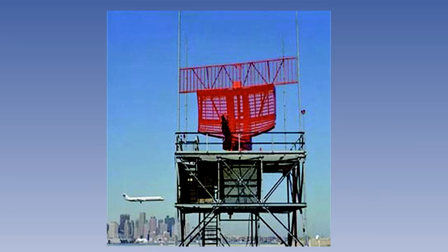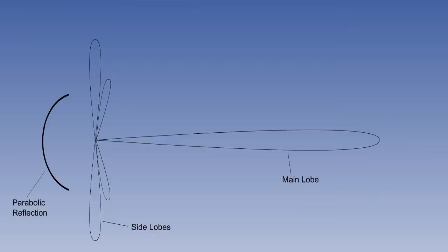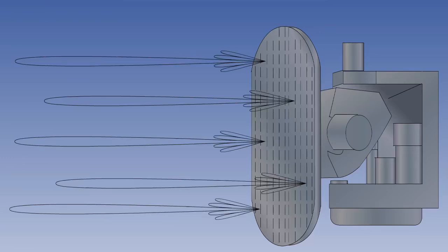The most common type of radar antenna is the parabolic dish or parabolic cylinder. These suffer from side lobes. A much smaller type of radar antenna is the flat plate or slotted planar array. The side lobes are smaller and need less electrical power. This makes it a popular choice for airborne weather radars.